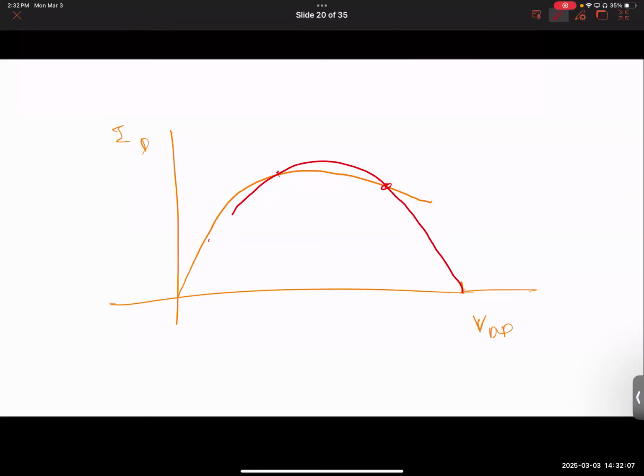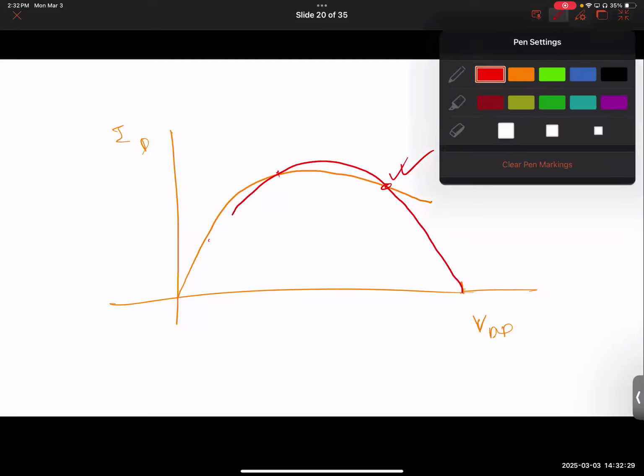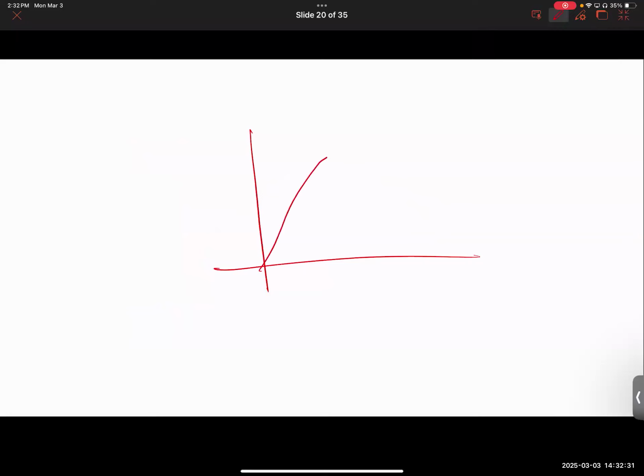That means the system could possibly be in multiple stable states, but that doesn't mean they will be all at once. When you go from low voltage to high voltage, one of them becomes the preferred Q point. When you go from high voltage to low voltage, the other one becomes the preferred Q point. So for one type of sweep, increasing voltage, one Q point; decreasing voltage, a different Q point. For conventional MOSFETs, it doesn't matter what you do.